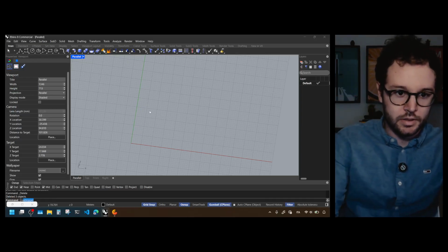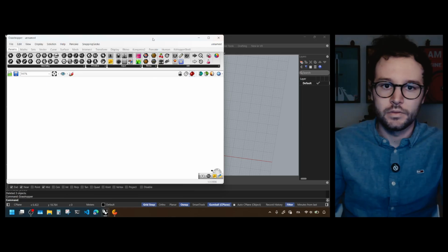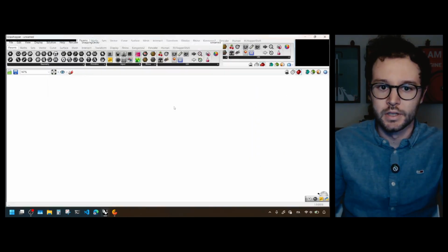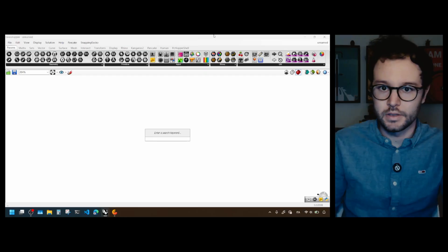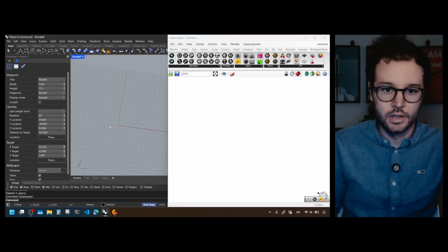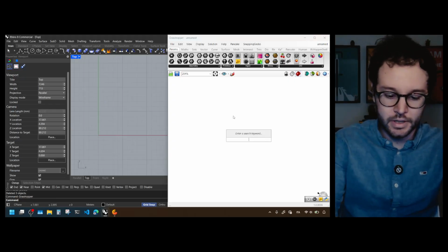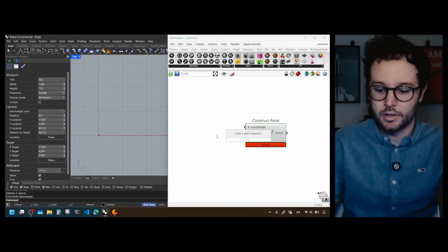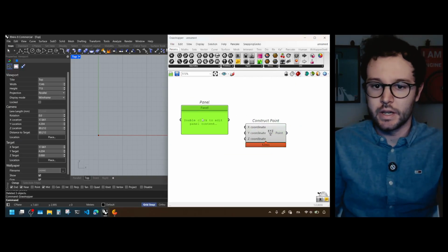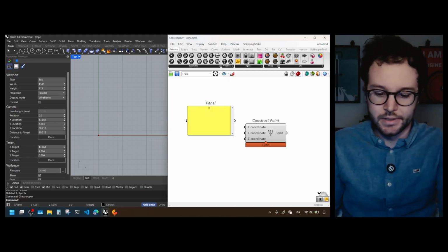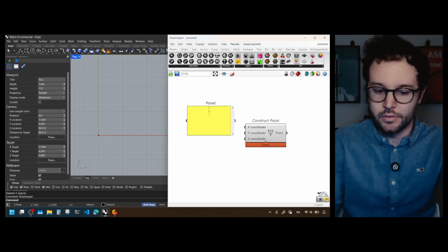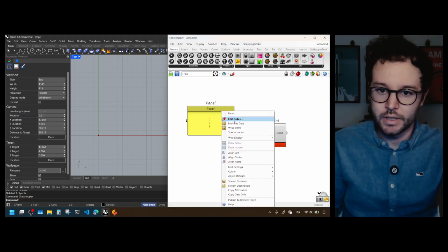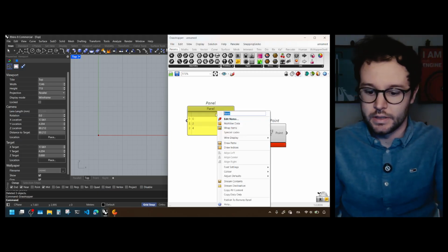And so, Grasshopper. Fine. Let's first define the 3 points. Let me split the screen so you can see both the space and Grasshopper. Okay, so x, y, z points. We need the x coordinates. We have that they are 0, 2, and 4. Multi-line data, of course. Let's delete the panel.